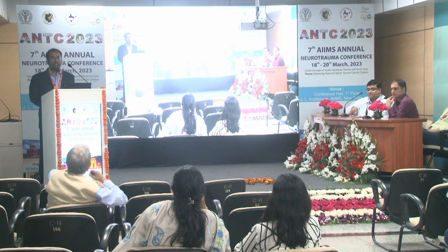Correct. So our team at UCLA was the first team to develop the most advanced electrode array for stimulation of the spinal cord, including the electronics to control it. So that is the next generation chip that needs to be developed. We had about 1,064 channels that we would electrically stimulate the spinal cord, cervical or lumbar.